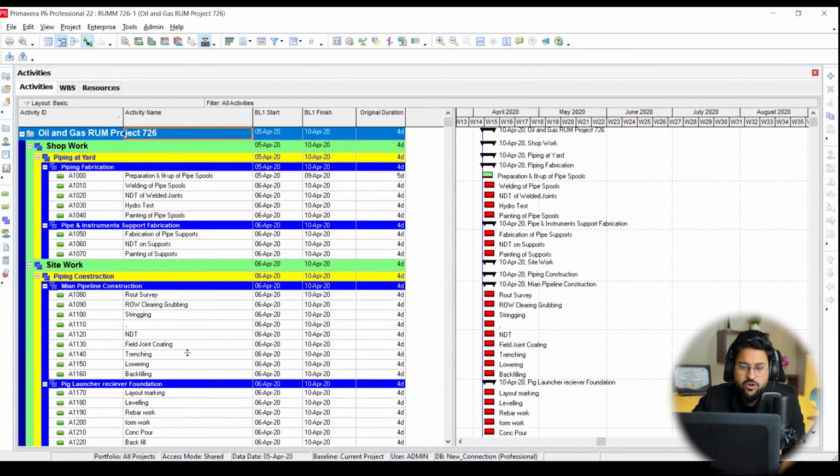So here we are. We need to understand now, from the perspective of Primavera P6, what the dashboard types are, and what basic settings we need to look at to work as an efficient planner and controller, right? As of now, you can see that within Primavera P6 there are three kinds of dashboards you can find over here. Okay, and this one, if I make it like this, is the activity table.